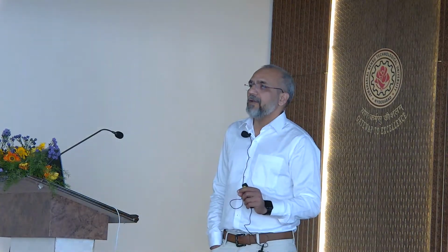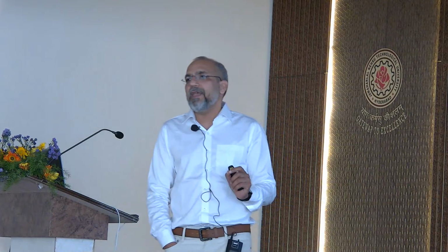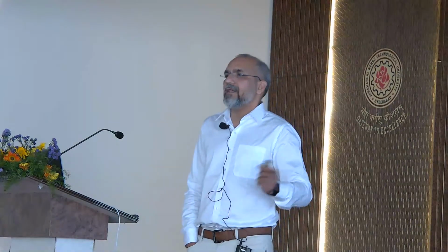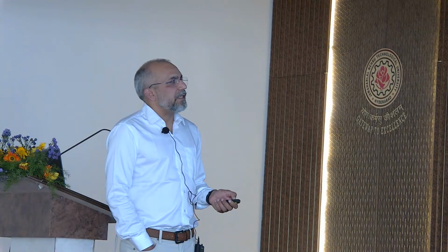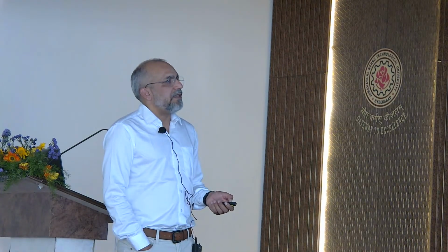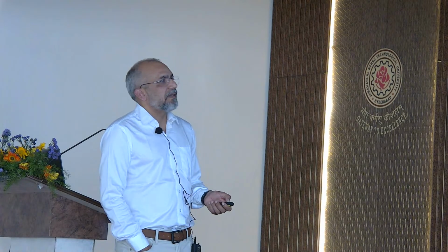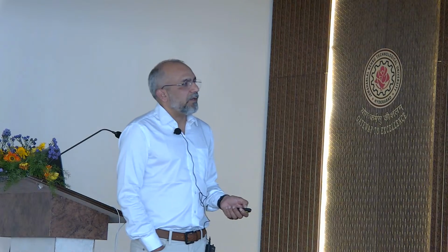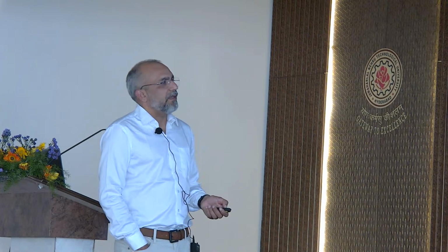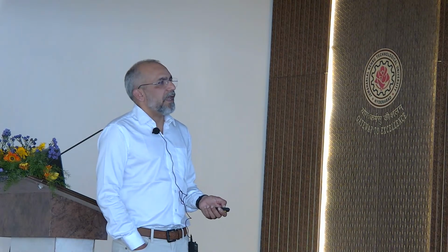So that was about the top-down approach, and the best is mechanical exfoliation, from the recently published article. The second is chemical vapor deposition. Again, it looks like a very simple technique. It has 3 steps: first is precursor injection, then the reaction site, and then the gas ejection module. So, 3 sections here. For example, to grow graphene, you have methane, hydrogen, and argon.